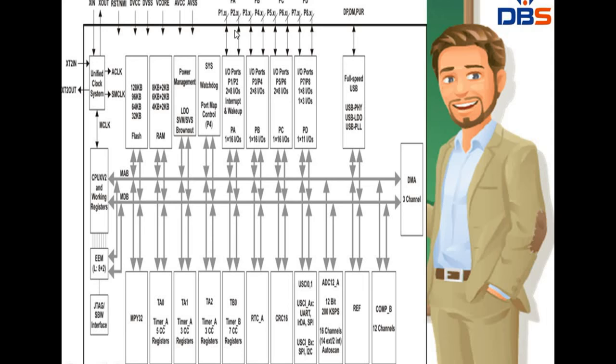and each individual port can be accessed bitwise or can be combined into word wide. That means if the data is 8 bits, we can access all 8 bits at once, and also access via port pairs.